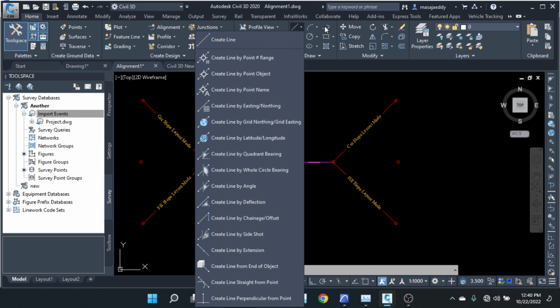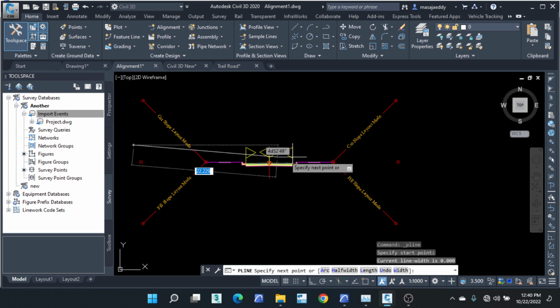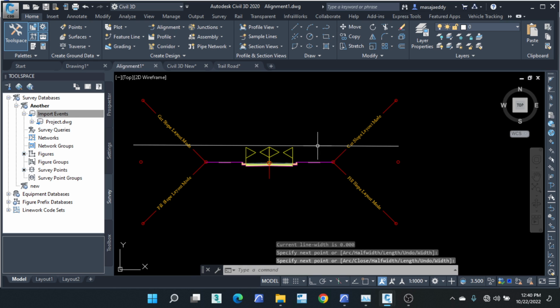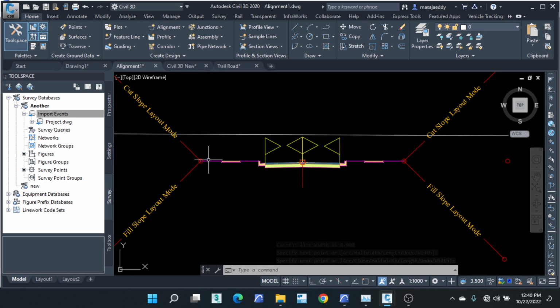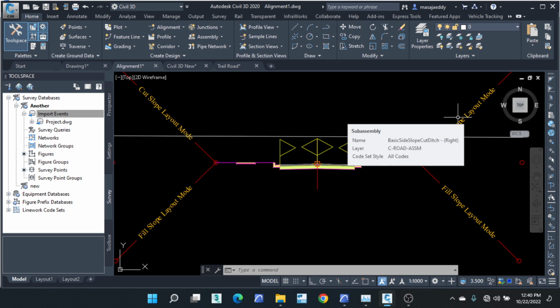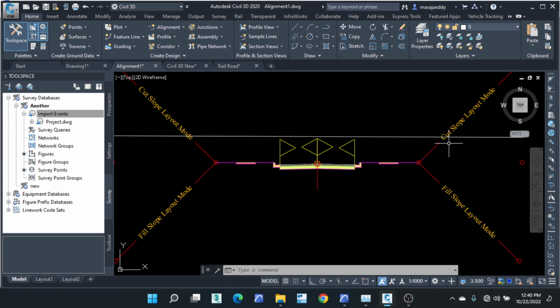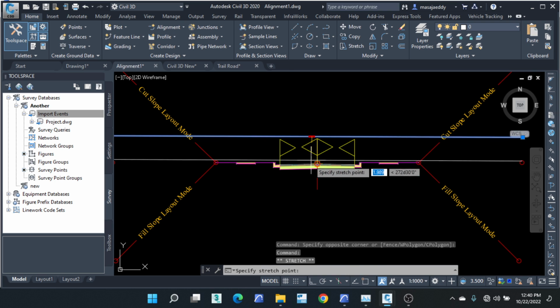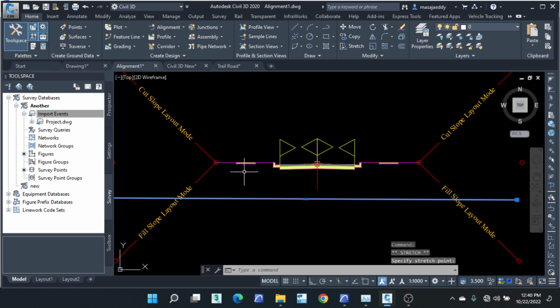What they are showing you here, let me just use this to draw. If for example this is my level of the ground, a cross section of my level of the ground, right? That means that I'm going to be cutting according to this, then come to my formation level, then also cut or grade according to my cutting slope, right? So I'm going to be cutting according to my slope. If for example my level is somewhere here, then I'm going to be filling, but according to this value. Now you understand? Okay, good.